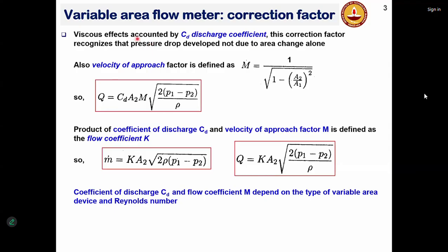It will not only depend on the viscous effect, but also there is going to be something called geometry dependent viscous loss, where if you increase the Reynolds number, the vortices and the circulation are going to be very strong. That will bring in additional pressure loss.